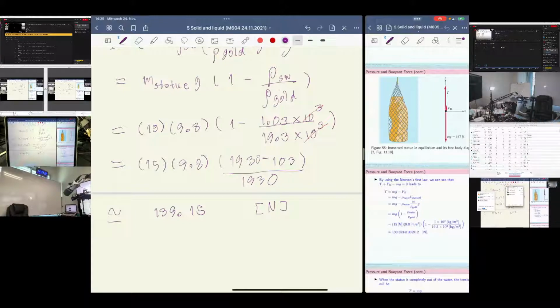For example, you have a glass like this, and you have liquid or water filled in. Just leave this one in the liquid, and it's going to stay upward, vertically like this, and you just read the scale. The scale you observe here is the number 3.4 or something like that. You get that value, and that value is the density of this fluid, the blue fluid here. And that's the first way.